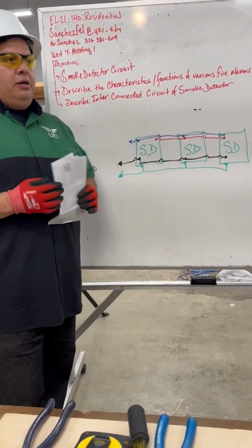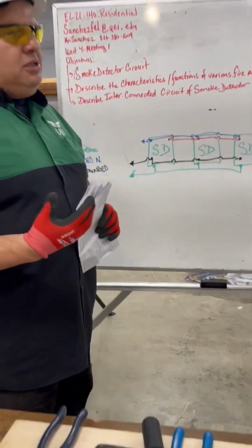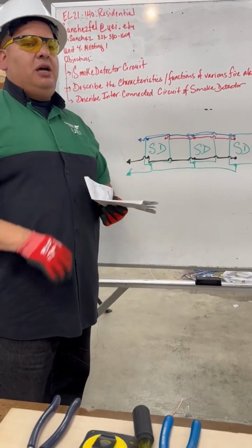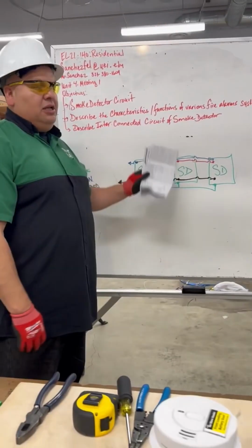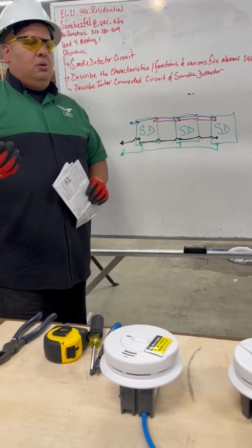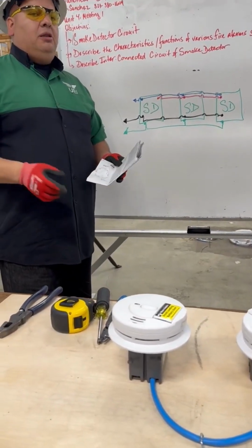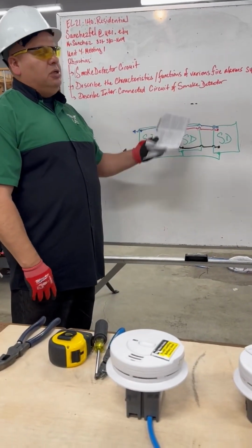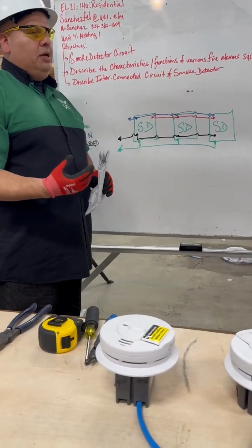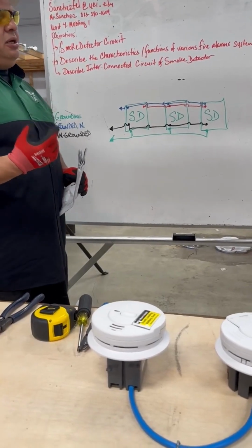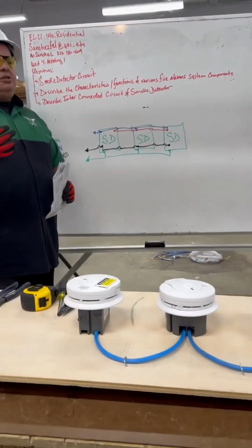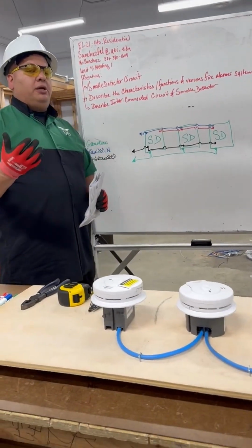I explained to a lot of my students, through past experiences with inspectors looking at their inspection sheets, the number one box on top of every inspector's list is the smoke detector circuit. Whether it's a plumbing job or some carpentry job they're inspecting, the first thing on every list of inspection is a smoke detector circuit check. That describes the importance it should have, because it's going to become an issue on the permitted project they're working on.